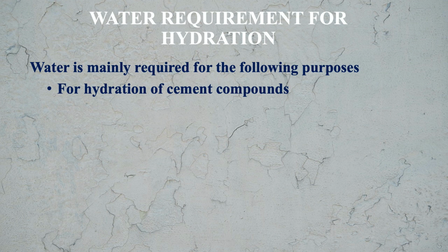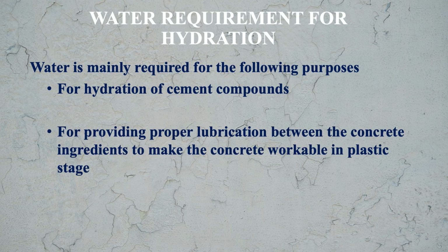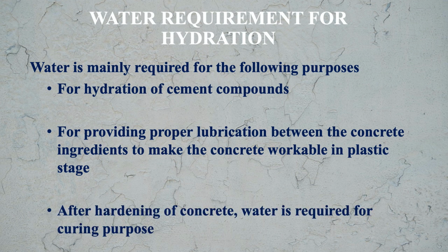Now let us see the water requirement for the hydration process. Water is mainly required for the following purposes. Number 1, for hydration of cement compounds. Number 2, for providing proper lubrication between the concrete ingredients to make the concrete workable in the plastic stage. And number 3, after hardening of concrete, water is required for curing purposes. So these are the 3 main purposes of water.